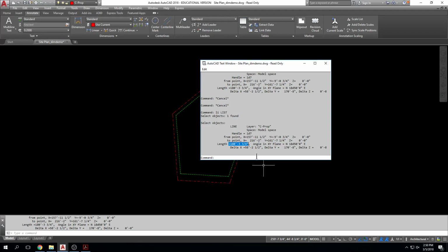To use it architecturally, you scale it up by a factor of 12. But if you want to redraw it, you have to dimension it as if it were in decimal inches. So we're drawing it to size it up and then dimension it so it looks like it's scaled back down. It's a roundabout way of doing things, but the system works.